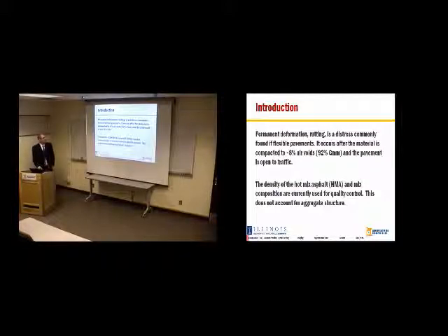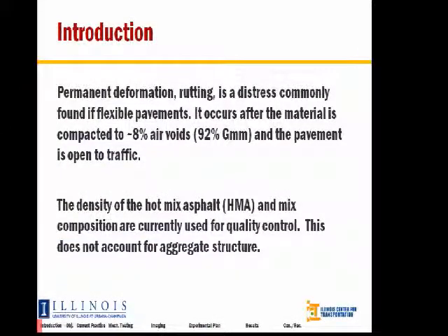So in terms of an introduction, I was focused primarily on permanent deformation, or what you will commonly hear people refer to as rutting of the HMA. Whether it's caused by a combination of warmer weather and heavy loads, that tends to be an issue that we face with a viscoelastic material such as asphalt. So anytime you have your HMA that incorporates that viscoelastic material, you run the risk of rutting occurring. And I'll show you guys a picture that I had taken locally, and chances are you've seen this happen on streets in this area as well.